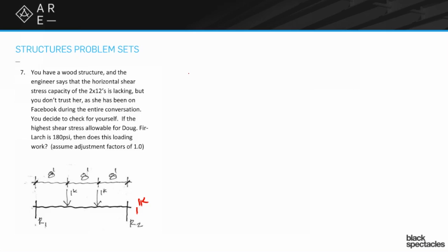But now we have to figure out how much shear stress we have. So that's going to be an equation that unfortunately in wood is a little different because of this first factor I'm going to put in front of you. But let me write out the whole thing first. So in wood, because you are dealing with a material that is looking at a horizontal shear, your point of worst shear is actually when you go vertical through the section and you're trying to split apart those horizontal grains. And so that's where this 3 comes from, it is a lot of differential equations in converting a vertical shear into a horizontal shear.